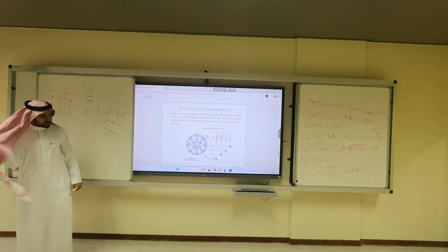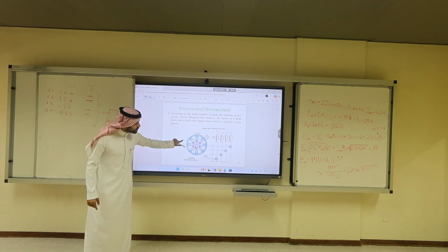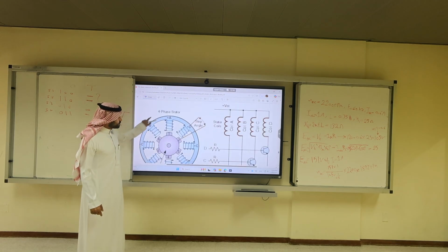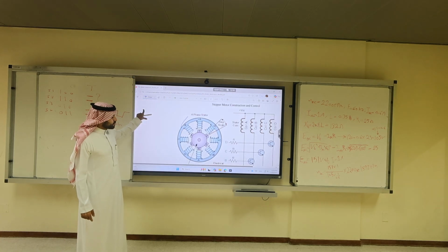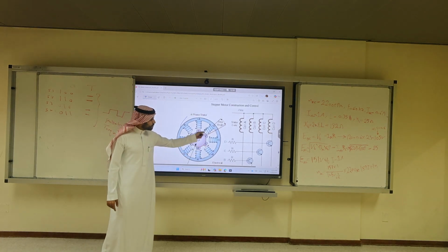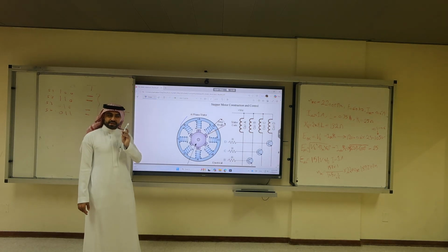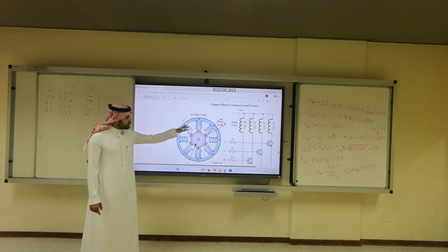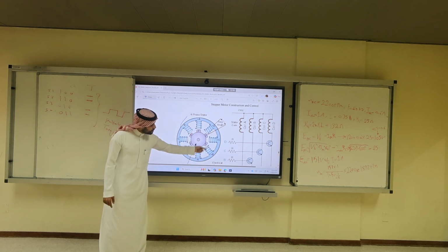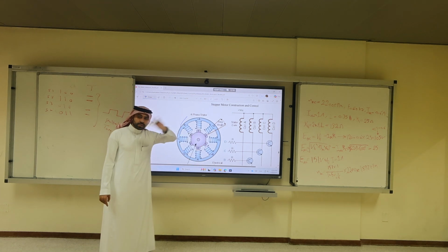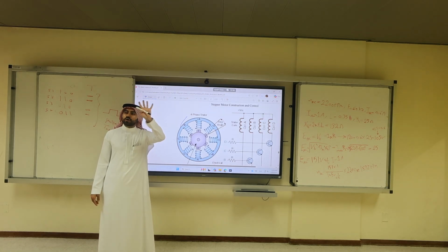Let me ask you a question. How many teeth in this machine? The stator. 8. 1, 2, 3, 4, 5, 6, 7, 8. How many phases do I have? Does it have to do with the number of teeth? No. It has to do with the letters. A, B, C, D, plus and minus. How many phases? It's a 4-phase machine.